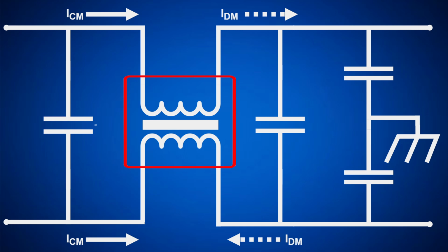The way it works is that when common mode noise is present, the choke generates a magnetic field that acts as a significant impedance to the common mode noise. The choke thus chokes or suppresses the unwanted common mode current. As I mentioned earlier, you will usually see common mode chokes on power and ground traces, but you can actually put these on any communication lines or clock lines that you want to, and you can try out different things to see what works for your particular design.